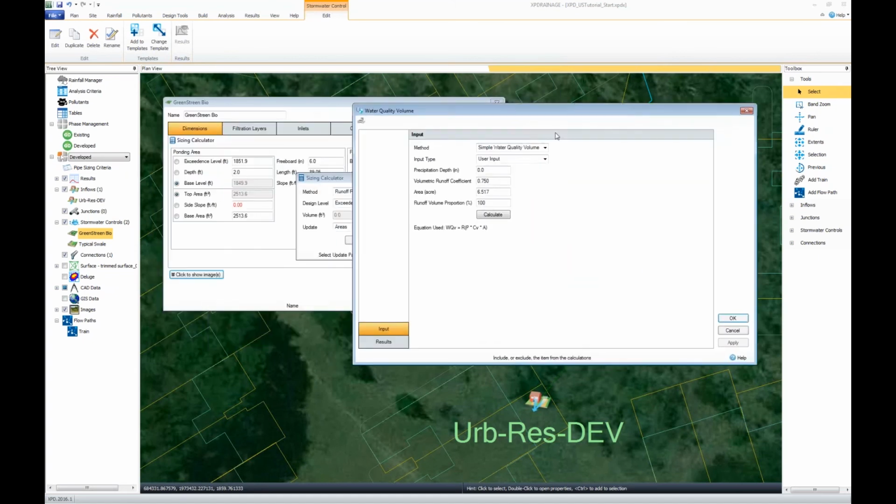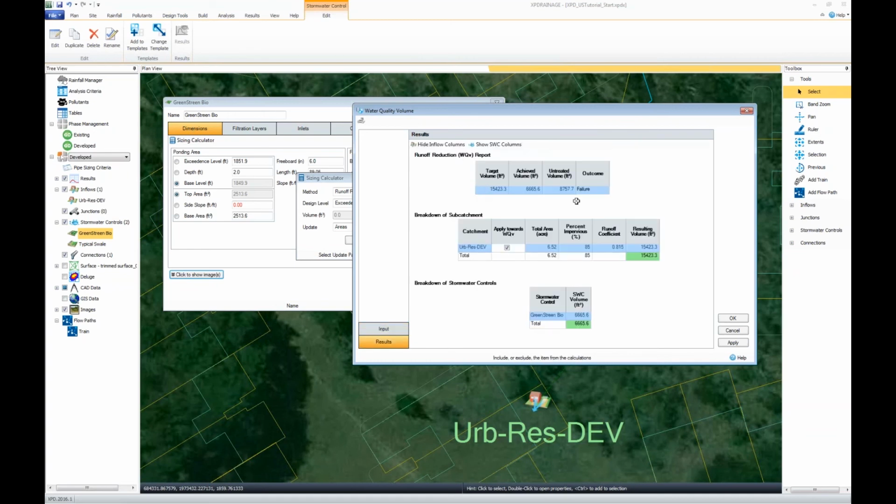So let's look at very simple runoff reduction, and just use the plan data. So all you have to do is enter in the precipitation depth in your area. So this probably going to vary between 0.8 and 1.2. Coastal areas perhaps more 1.2. Let's just say 0.8 just for grins, just to start. And we'll see probably this is a report. Of course, we could print and we could show.